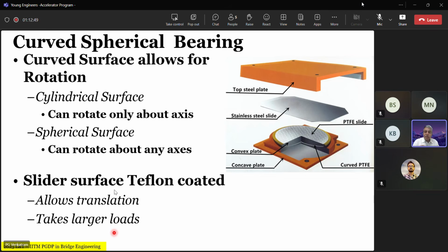You remove them after you have placed and grouted. But that is still not the main reason. You don't assemble anything at site. The elastomeric bearing also comes from the factory ready to use. Potted PTFE also comes from the factory ready to use. You don't assemble them at site at all. If you're thinking in those terms, forget about it.